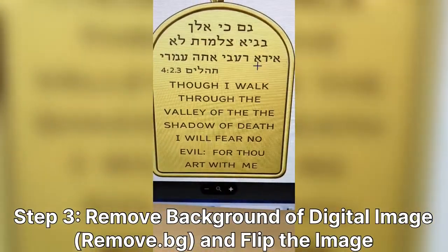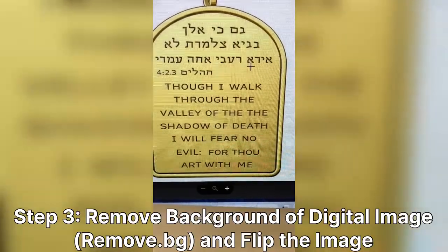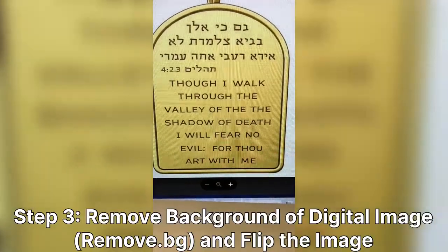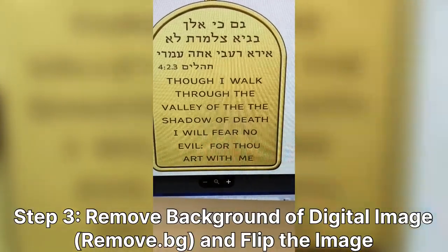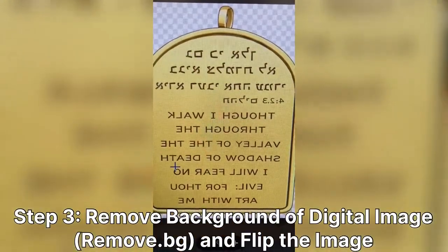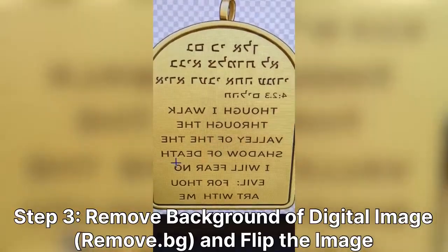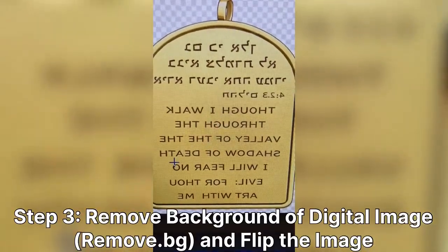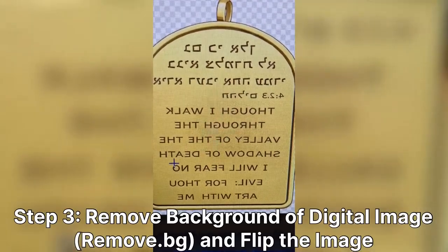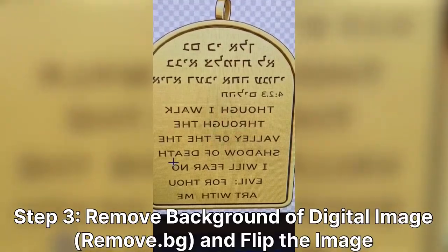I removed the background of the digital image and I flipped the image. This is something that I had to do throughout testing. I had to test this a few times to get this to work right on the next step. So make sure you clean your image up. You don't want anything in the background and you want the image flipped. So as you see now, all the English lettering is moving backwards. It's all mirrored backwards. It's all flipped and there is no background. As you see the checkerboard pattern in the back, that means that there is no background. You can just save this as a PNG.